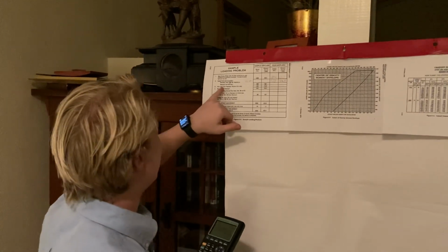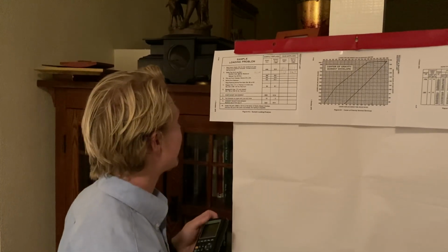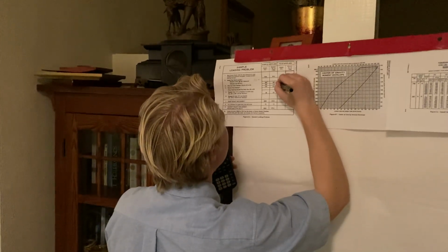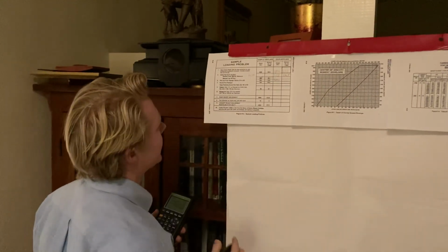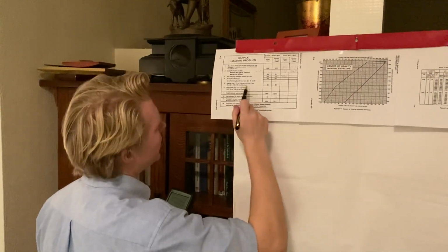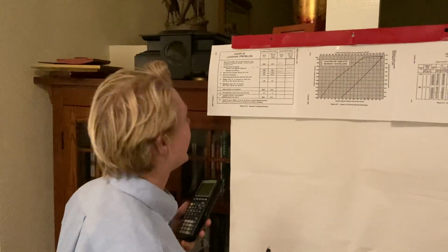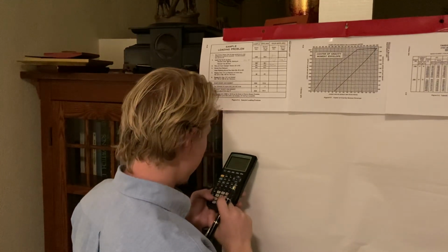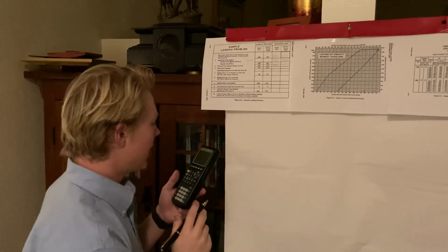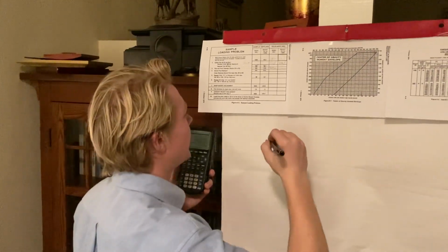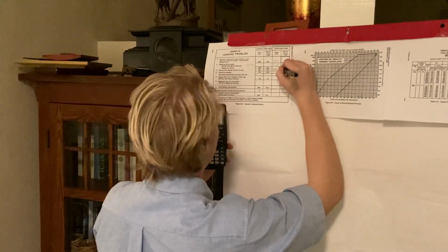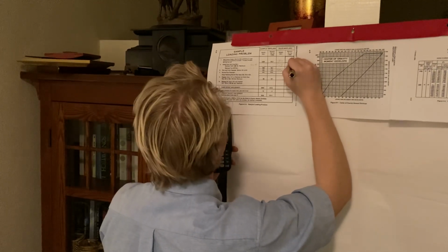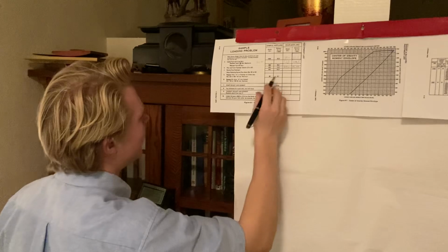We're gonna use standard weight for the pilot and the front passenger of 170, so that's 340 pounds total. And it's adjustable seats from 32 to 50. We're gonna say they're around the middle, which is at positive 41. So we multiply 340 times 41, and we get 13,940. And so that in thousands is 13.94. And we have no other passengers and no other baggage.